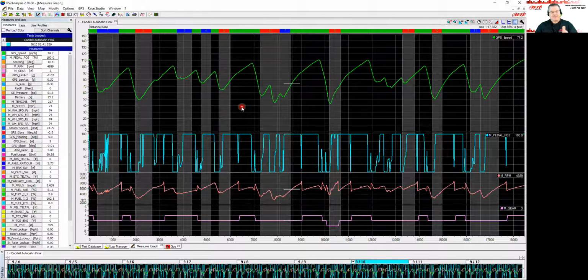But the shortcut that I want to teach you guys today is if you take your mouse and you hover on the scale bar of the channel that you're after, just here somewhere near the middle. If you get way to the tip top, you'll see the cursor will change a little bit, and then towards the bottom, we just need to be out of that area. So I just say hover about in the middle and double left click.